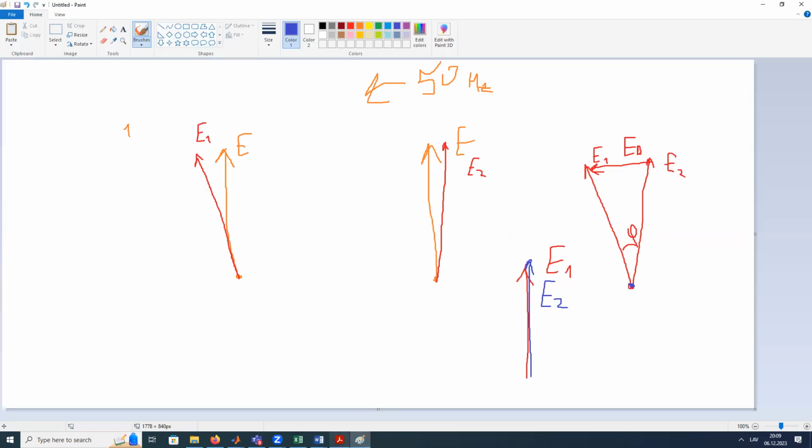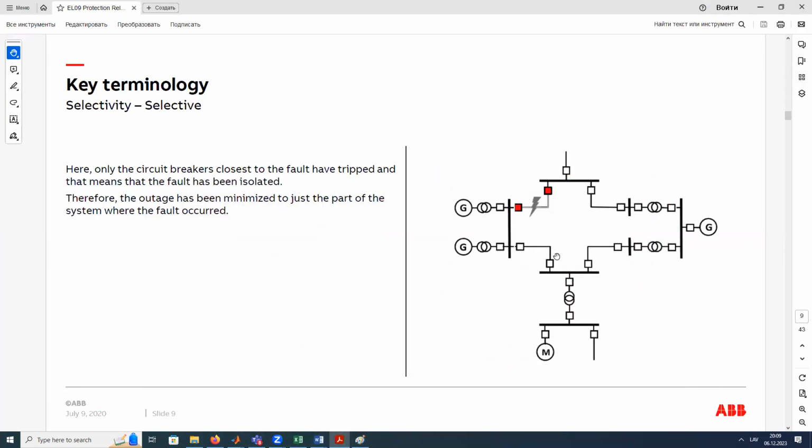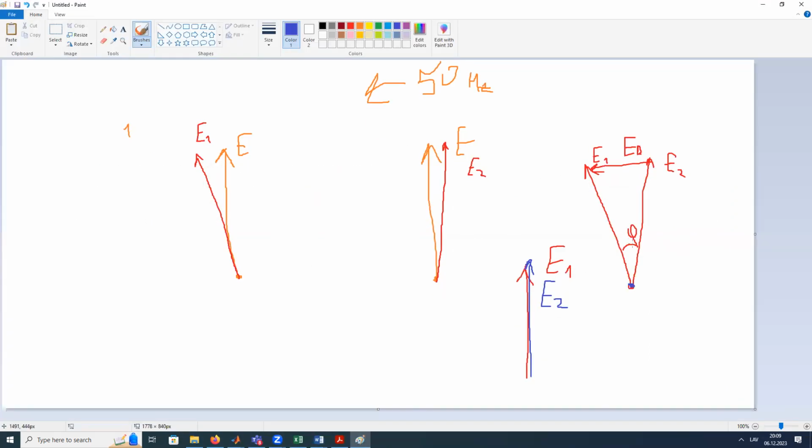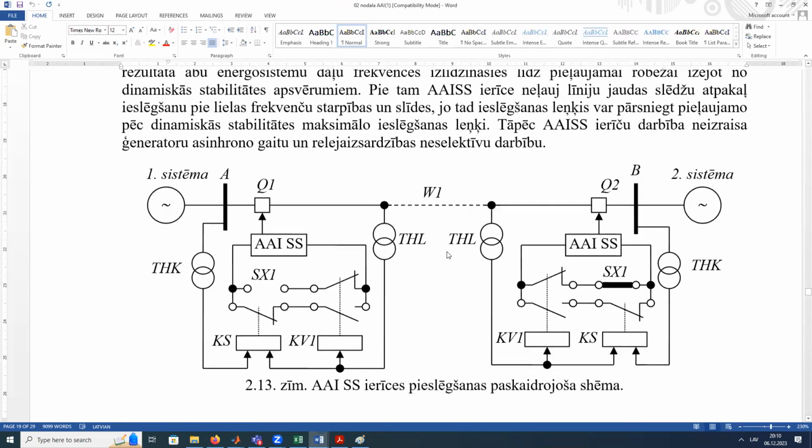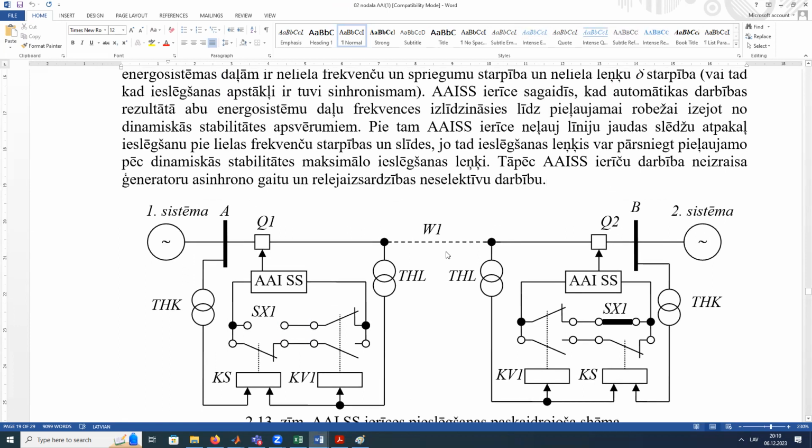So the reclosing for this type, when we have a loop, when we have a connection of several parts of the power network, could fail due to the angle between them. We could wait, without success. They are not synchronous, still not synchronous, still not synchronous, because they are both rotating. We are just waiting a moment until they come close together to connect it back. That is what I wanted to say in a few words: reclosing for two sides is quite a bit more complicated when we are talking about a transmission line connecting huge parts of the power network. So this reclosing is a very complicated thing, unlike when we have a serial connection. Okay, now it is all.